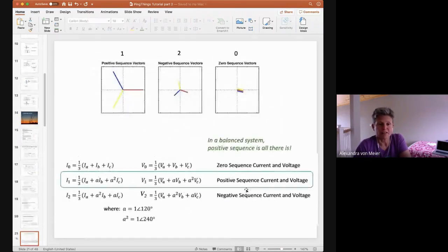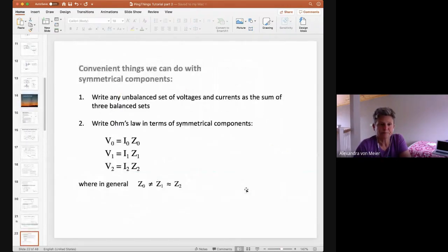The relevance of symmetrical components is that you can do very tidy analysis of 3-phase systems. Instead of taking into account all the cross-referencing relationships between and among all the phases, which basically would mean writing down 9 equations, you can represent the system in terms of the sum of 3 balanced or symmetrical systems. So it makes the math easier.